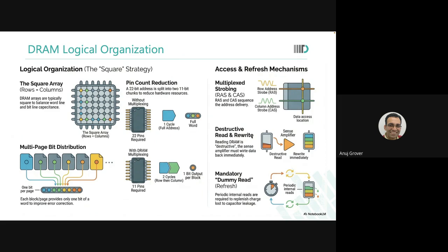So where an SRAM would have worked with n number of bits, DRAMs, by virtue of their density, and also DRAMs being the main memory and so on, they are expected to be larger. They need more address bits. And more address bits also means more area. Where does it mean more area?